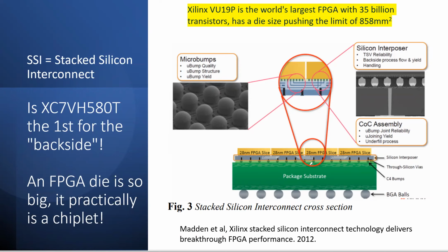They put a lot of FPGA on a piece of silicon interposer, so they could do what they need to do. And they put the silicon interposer directly on C4. But that's that time, that's what's been done. And then they have this TSV already, so they already did it. The reason they have to do that is because the die is so large.